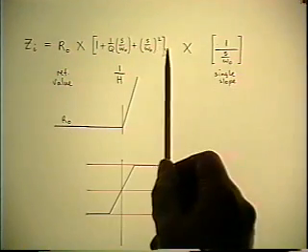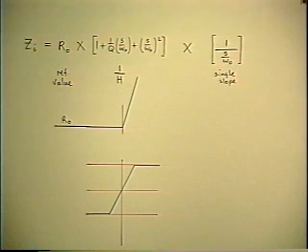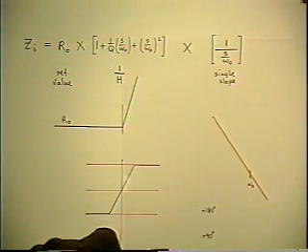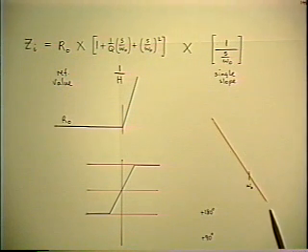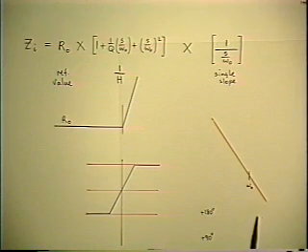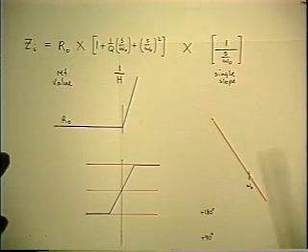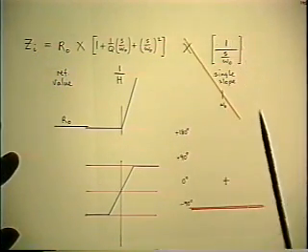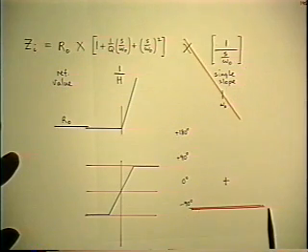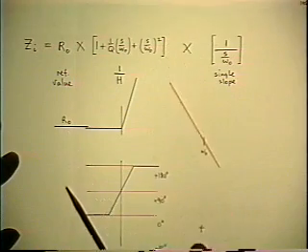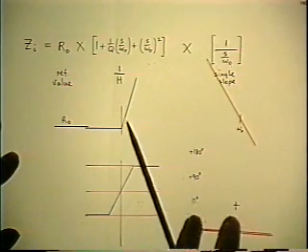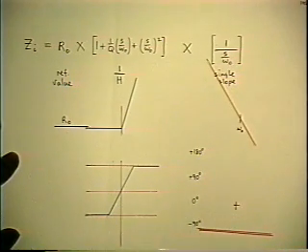So that takes care of the first two terms now. Now I still have a third one to do. That is a single negative slope, minus 20 dB per decade, and a fixed phase angle of minus 90 degrees. Again, all I have to do is position this both vertically and horizontally to make it fit on properly with the picture that I've got already.